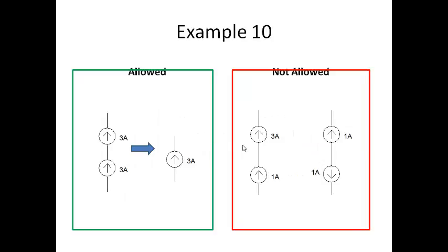when two current sources in series have different magnitudes. This is 1 ampere, and here suddenly it cannot be 3 ampere, so that is not possible. Similarly, this thing is also not possible. As in case of AC voltages, if this is an AC quantity and this is also an AC quantity, then these two current sources, when connected in series, must have the same magnitude, the same phase, and the same frequency, so that they can be connected in series. Otherwise, they cannot be connected in series.